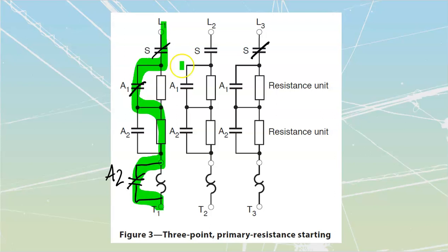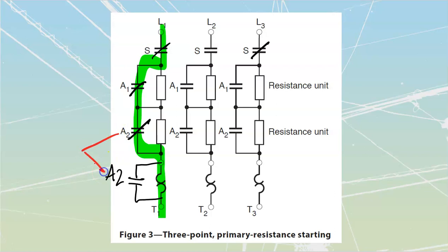And then if I get all the way over to my step 2, that would fire A2, which would close this one and would simultaneously open that one, which would mean that now my current would pass through here and down. Note that this would be interlocked. It would be tied in so that by the time we get to A2, this thing would automatically have to open. Then as soon as we shut this thing down, this would reclose once again if it wasn't normally closed.